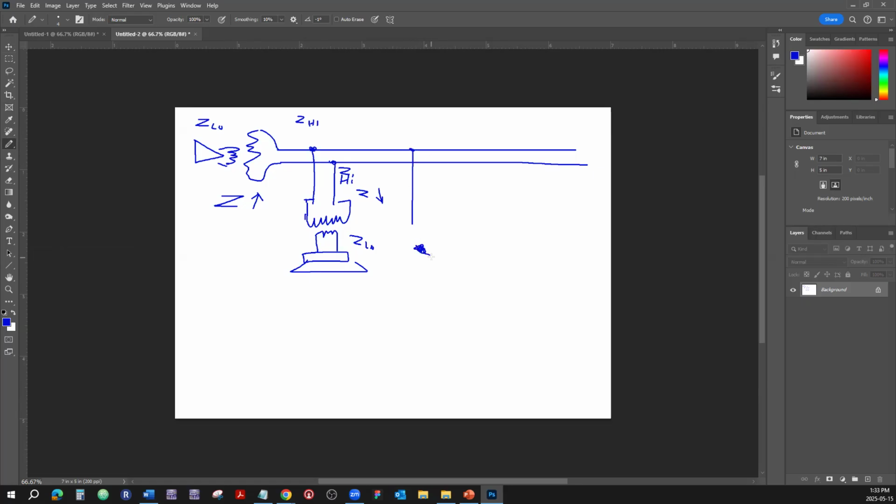All right. I'm just going to draw that this is it here. We can just connect that and connect one more. All right. And connect one more speaker station, because this is going to be called a speaker station. It will be a loudspeaker connected to a smaller transformer, but it does the same thing. It steps down the transformers back to 8 ohms. This way, we don't have to worry about the series parallel combination between the speakers of the same impedance, because the transformers are going to work it out between each other. And we could just keep adding until we run out of power.